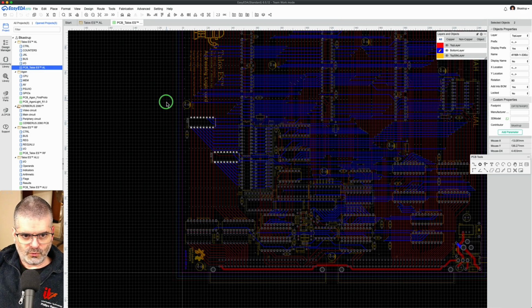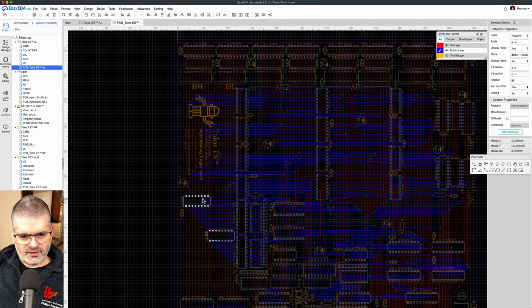And therefore, afterwards, they go through the 33 ohm resistor networks, which are there to absorb reflections after the selection is made. So when the signals go along these lines, and you see there are branches, there are always branches, you get reflections. And because I didn't want to eliminate all the branches and make the board design very difficult to understand, I wanted it to be clean and didactical. Instead of removing all the branches and making everything a snake, I put the 33 ohm resistor networks there to absorb some of the reflections.